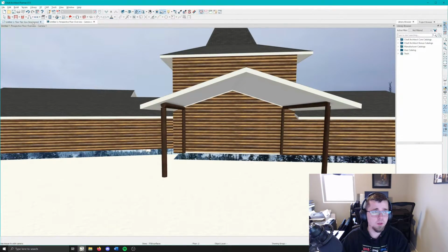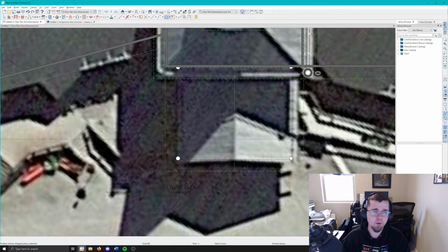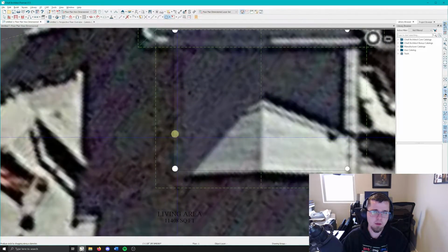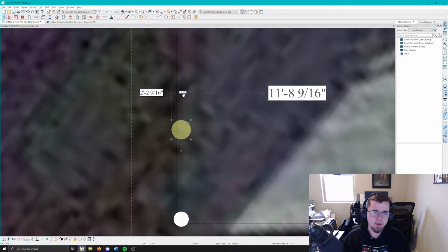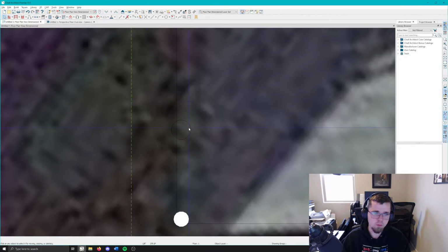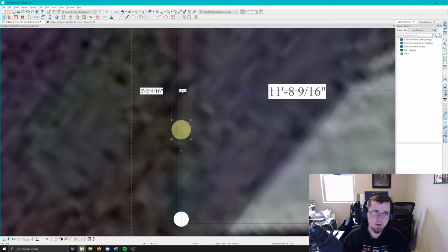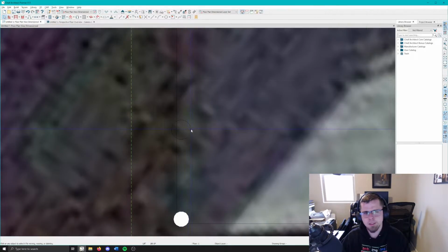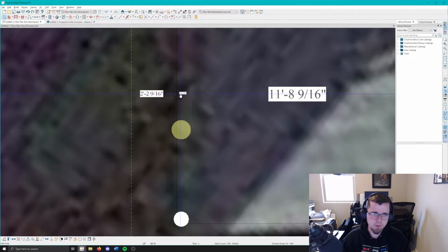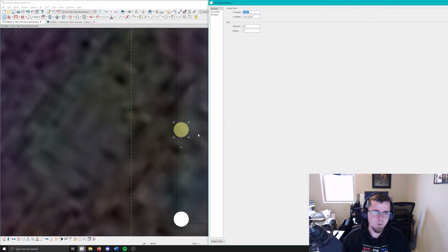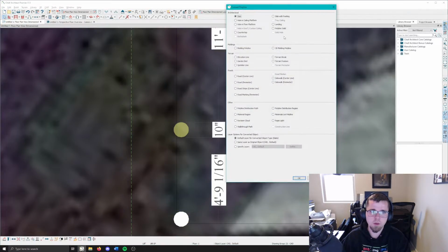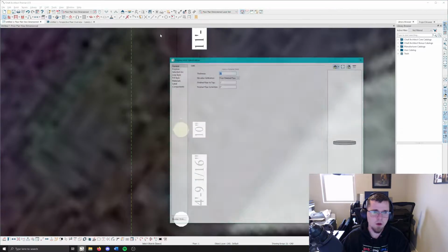But normally it's actually going in and dropping in, and I'll show real briefly how that normally would work, because if I'm going to be cantilevering it a little bit, I'm going to take this, it didn't work, but I've drawn just a circle. Oh, good. Keeps grabbing that wall every time I try to click this dimension. All right, 10-inch. Let's center it across that wall. I'm going to take this, turn it into a solid object.